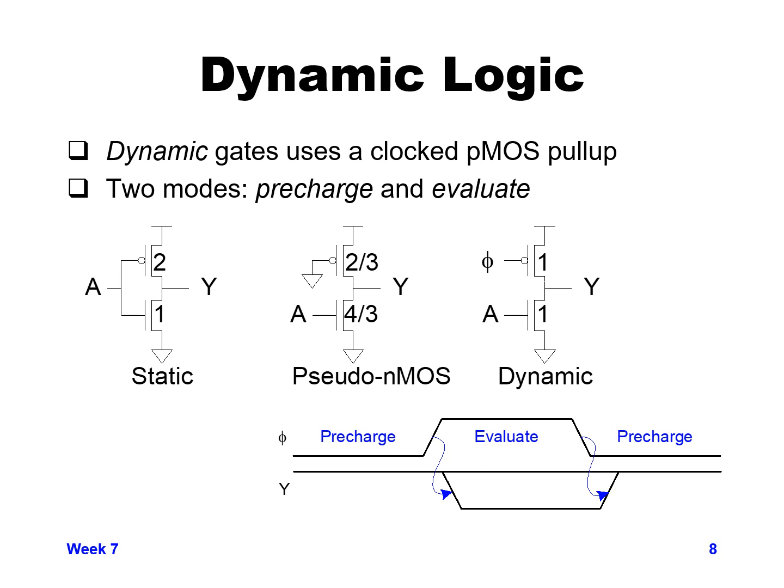In dynamic logic, the PMOS device is connected to a clock, and so we only have the PMOS device on for half of the clock cycle, and while the PMOS device is on, it's charging up our output and creating a positive charge there, and then when we turn that device off, that's when we can turn on or not the input A.